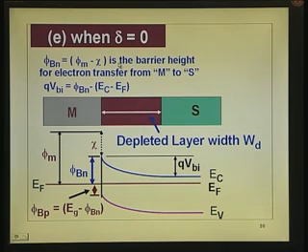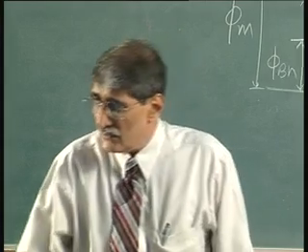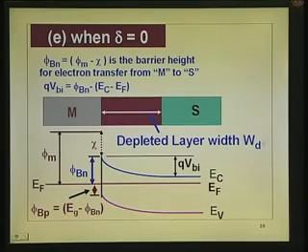Chi is fixed by the semiconductor; it is independent of doping, and it depends only on the work function. Then this built-in potential depends, in addition to phi_bn, on E_C minus E_F, which is actually the doping level. If the doping is increased, the Fermi level goes towards the conduction band, so if it moves up, you will have a slight reduction in V_BI. We will come back to that discussion. Right now, what I am focusing on is this quantity, which decides the built-in potential, guided by the doping of the material.